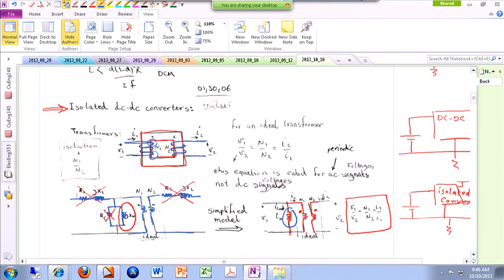Over here, we are talking about coupled inductors. The whole thing is very small. You can actually hold it in your hand. And because the frequency is high, for instance 100 kilohertz, you have to use a different material. Usually it's iron powder or a ferromagnetic material that can handle such high frequencies. Also, the number of turns is relatively low. For instance, it could be only 10 turns on the primary side and 20 turns on the secondary side, something like that. It's not like 1,000 turns on the primary side or secondary side.